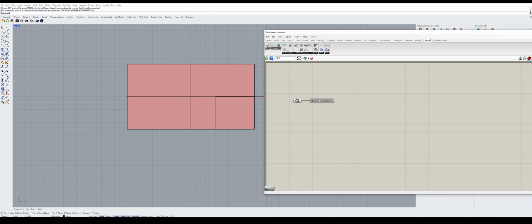And the next step is to set the load and constraint on the surface. So we go to Domain 2D, click Load, drop it to our canvas and click Support 2D Curve, drop it to our canvas and connect our components. We'd like to put our constraint on the left side and the load on the right side. So we put our value 0 to the constraint and our force downwards, -2, 1, and 0. Connect to our Y component.